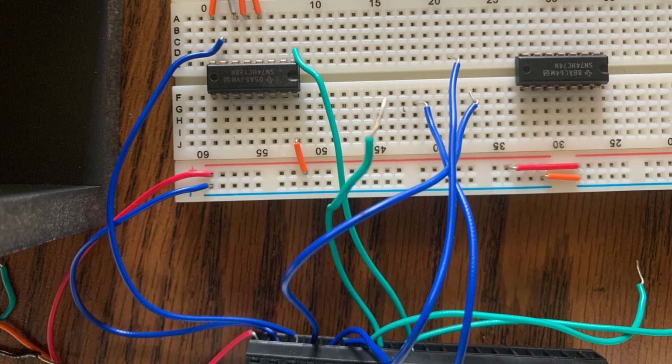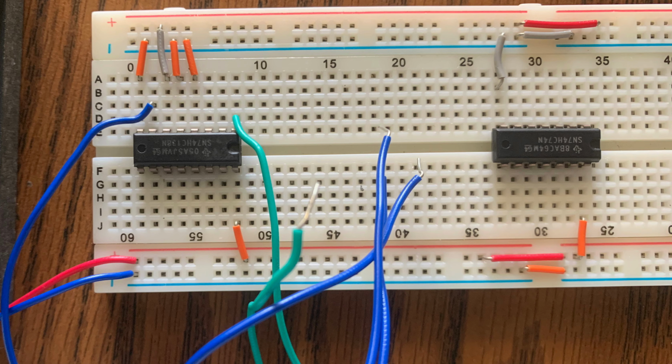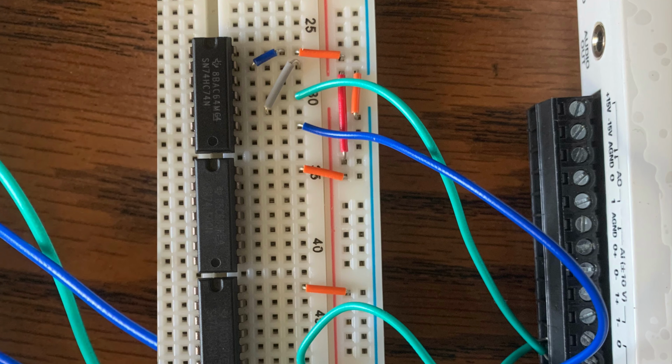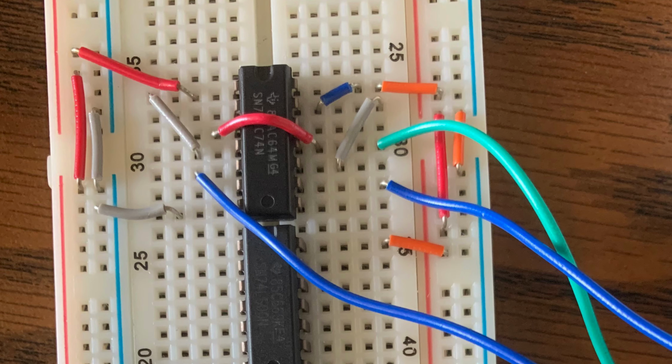Next, we'll set up the flip-flop by placing it on the breadboard, leaving space for logic gates in between. We supply power to the chip, and we also connect an unused output from the MyDAC to the clock input on both sides of the board. We connect the clear and preset pins to power in order to avoid using them. We also connect the output to pins 4 and 5 on the MyDAC so we can read the current state.